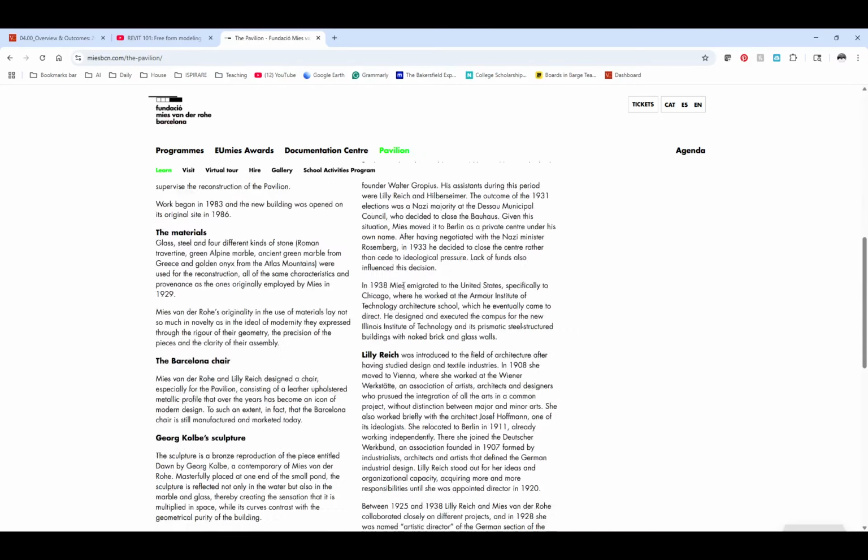So I'm going to come back here. I'm going to turn on hidden line, and I am going to model these walls, everything in blue. So I'm going to isolate them, and then I'm going to model these things using a mass tool, and it'll make a whole lot more sense here in a second. So using the Mass tab, I'm going to do an in-place mass, right? And then I'm going to create some geometries around these walls.